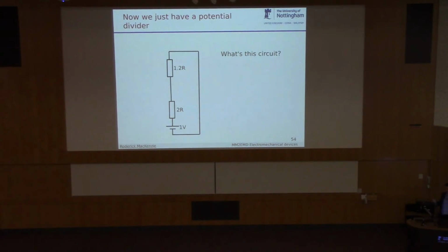So let's go. I know it's getting a bit intense, but we're going to stop this in like three slides, and you'll see where all this fits in and why we're doing it. So now we can very easily calculate the voltage over this resistor, and we figure out using this potential divider rule that it's 0.375 volts. So that's the potential drop over here.